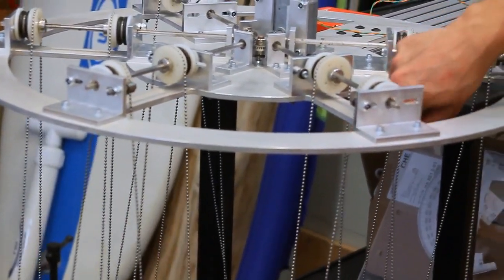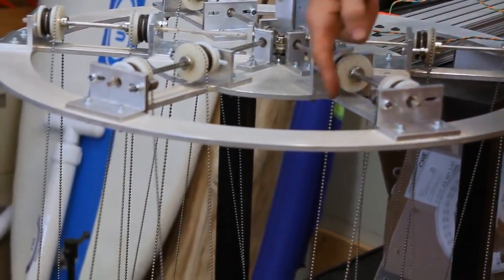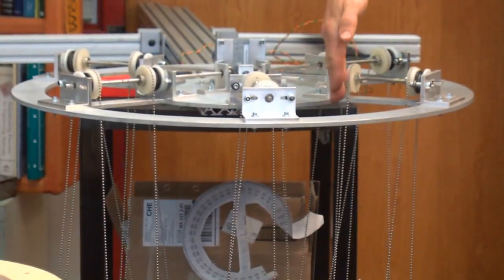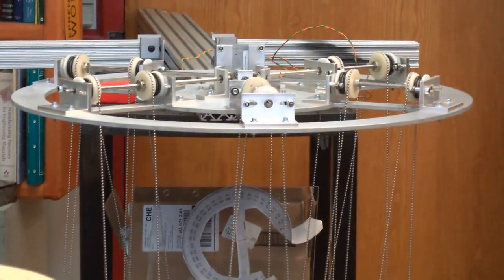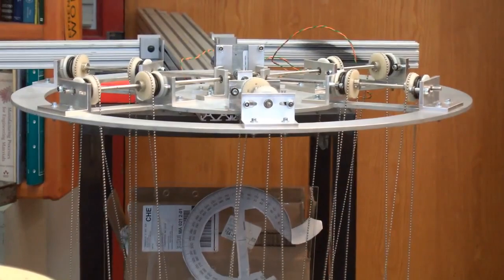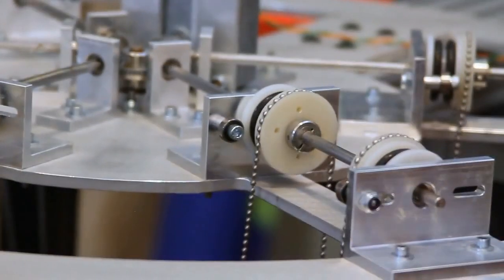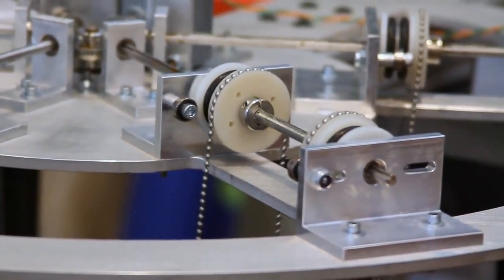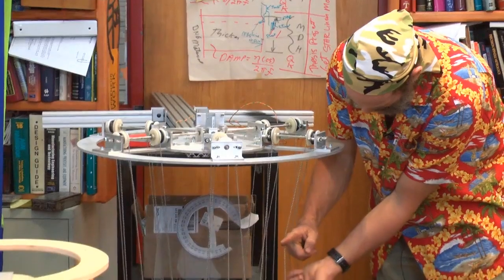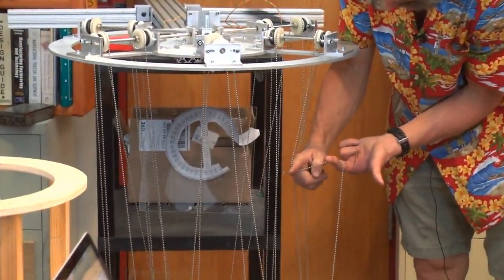So the bead belt comes in, and even if this is moving, it's going to dynamically keep itself from derailing or coming off the sheave. This allows you to have a structure where the pulley could even come at a fairly large angle, although generally what you do is you bring the bead belt down around an idler pulley and then off to the side.